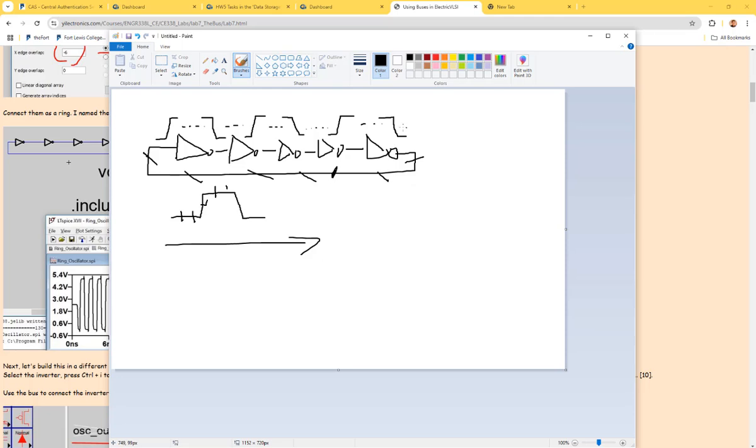And eventually, after this is put down, it will go through the same time delay and then be put up. Depending on the size of the transistors, you will get different time delays. A bigger area of the gate will give you a bigger capacitance underneath the gate, and a bigger capacitance will give you a longer time delay. Eventually, when we deal with the digital models using the parameters from the textbook, we will be able to calculate an estimate of the time delay later. But now we don't have to worry about that. Just know that there will be a time delay.